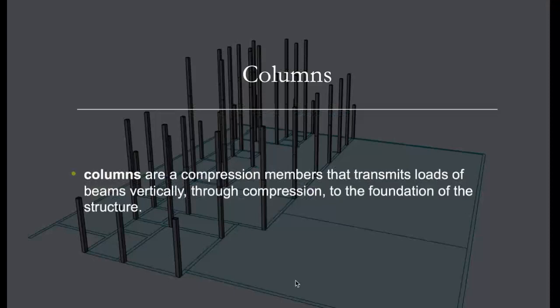Assalamu alaikum. My name is Mohammed Al Thani, and now I'm going to talk about the structural component that will take the load after the beam, which is the column. Columns are compression members that transfer the loads of beams vertically through compression to the foundation of the structure. And there are different types of columns, based on the type of reinforcement, type of loading, slenderness ratio, and shape.